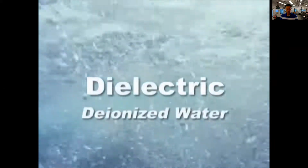But what's all this liquid? Well, that's the dielectric. Deionized water, really useful because it doesn't conduct electricity. In wire EDM, the liquid dielectric controls the sparking, cools the process, and flushes away those tiny particles as they're removed. All very fast, about 1 million sparks per second. The particles themselves are each about the size of a particle of smoke.